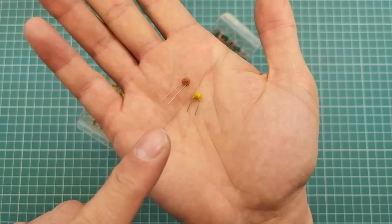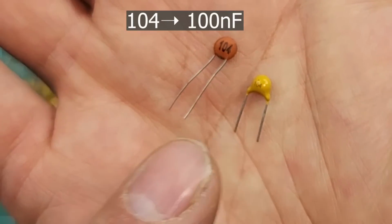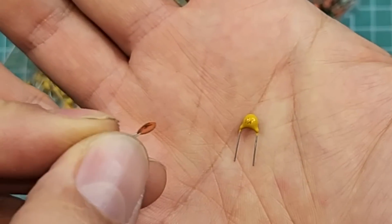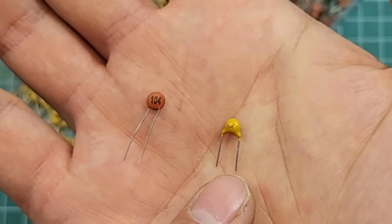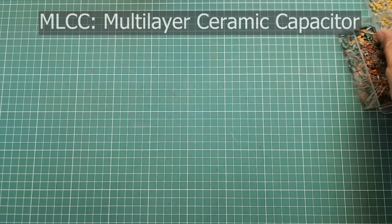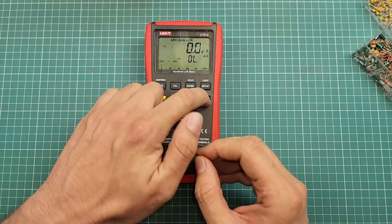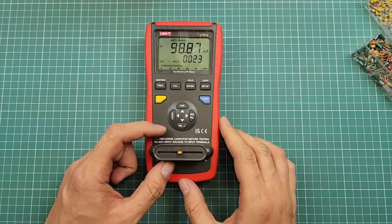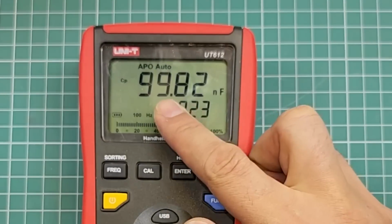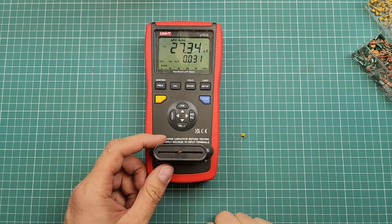As you can see, both of these capacitors are 100 nanofarad capacitors. This one is an ordinary single-layered ceramic capacitor and this one is a multi-layered ceramic capacitor. If I measure the capacitance of the multi-layered ceramic capacitor at 100 Hz, it seems okay. It's near the expected 100 nanofarad. But if I measure the ordinary low-quality ceramic capacitor, you can see that the capacitance is not very accurate.